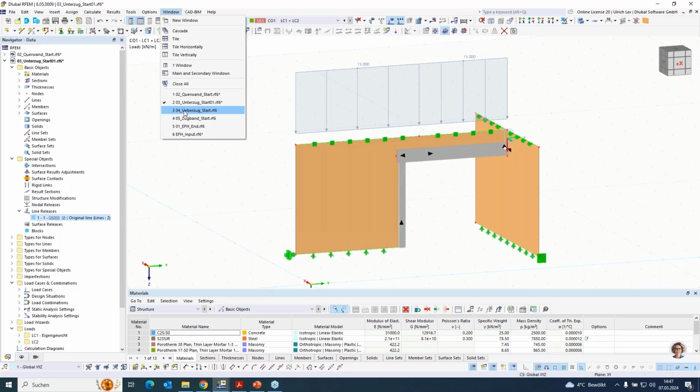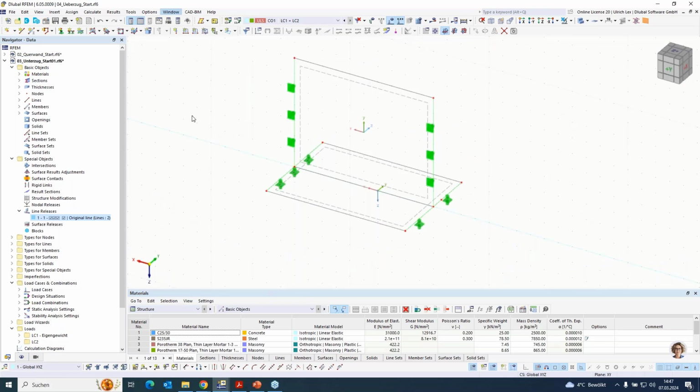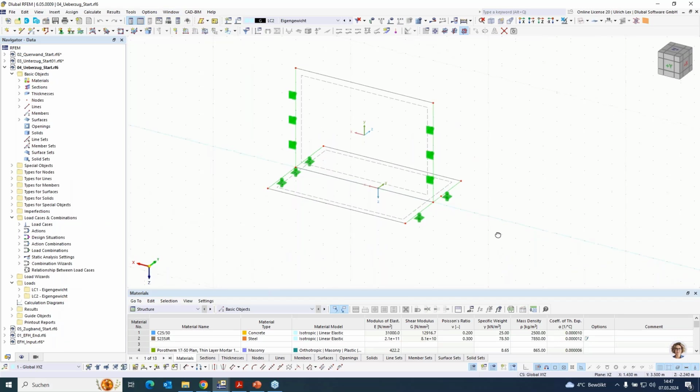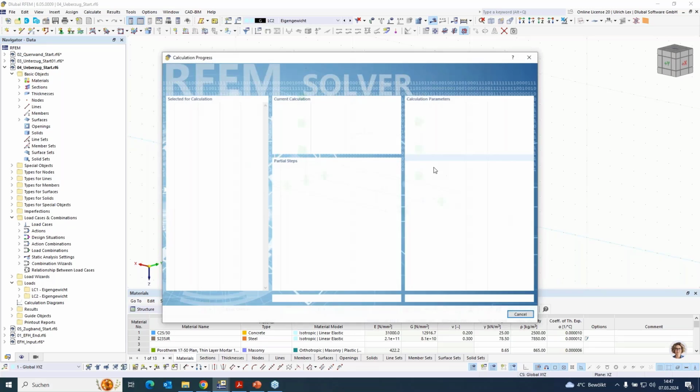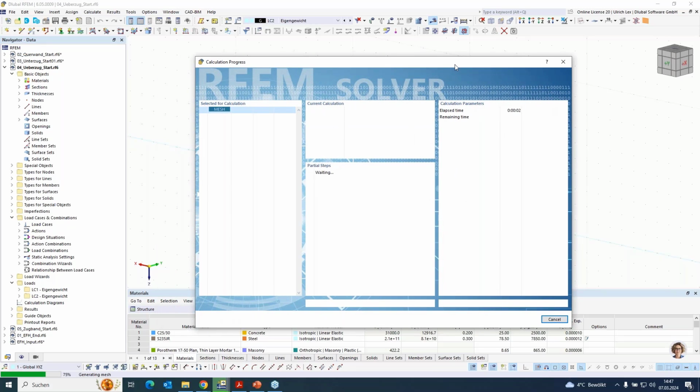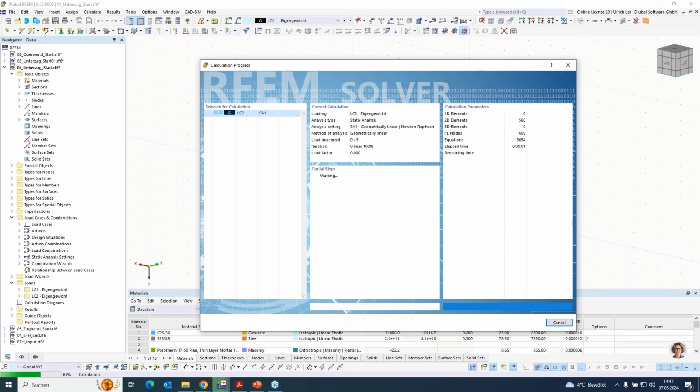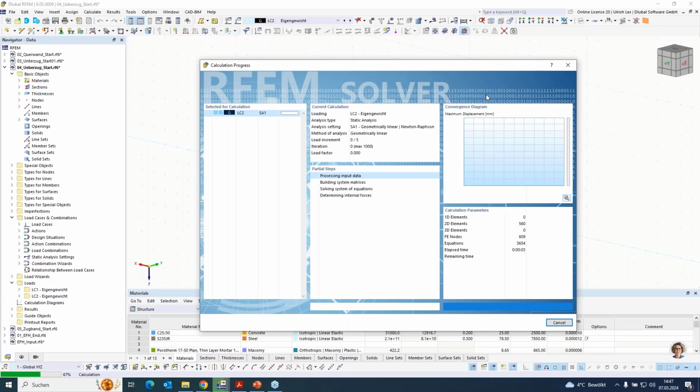When you have something like a wall above a concrete slab, where you have no support in the floor below, then when you take a look at the results, you will see that the masonry wall is acting similar to a beam.